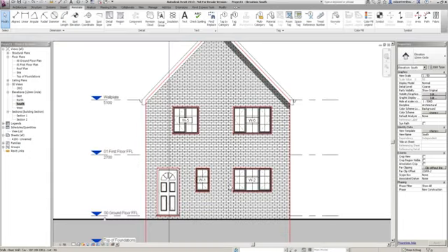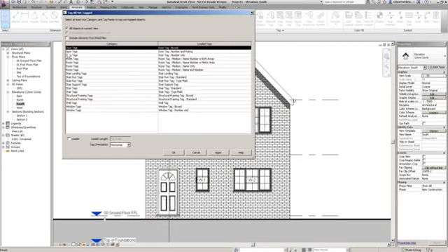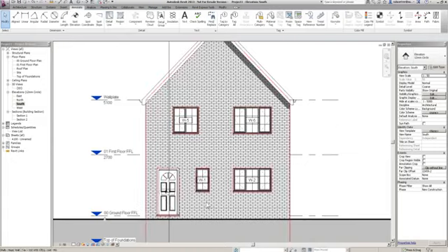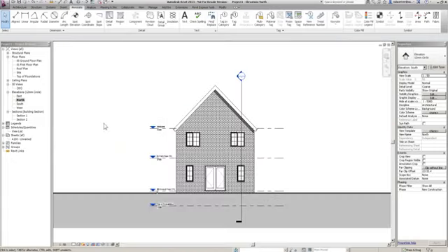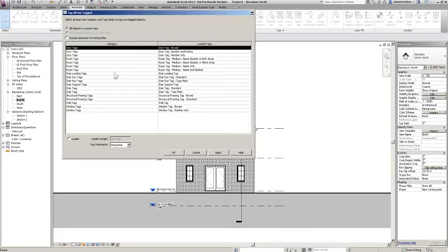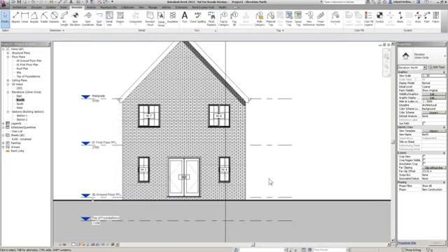It's going to tag those exactly the same tag as it will show in your plans. Again, I'm going to do my door. Okay, so tag all doors, boxed. Okay, done. As we can see just there, it's tagged. Let me go to my north elevation. I'm going to tag my doors and windows this time. Okay, done. That quick. Let's go back into my plans.